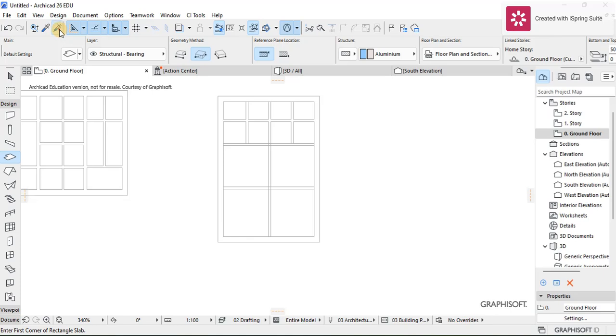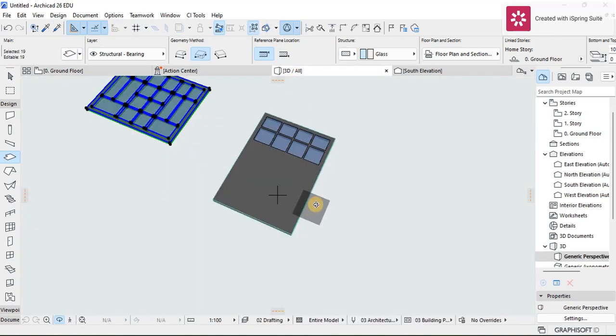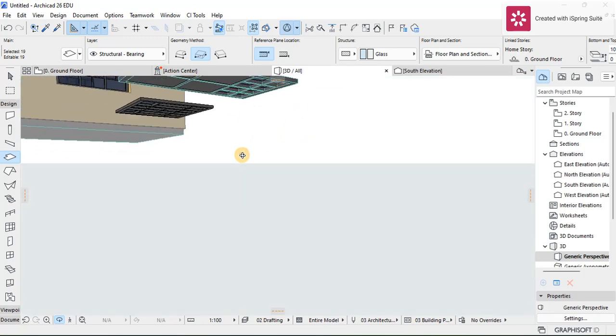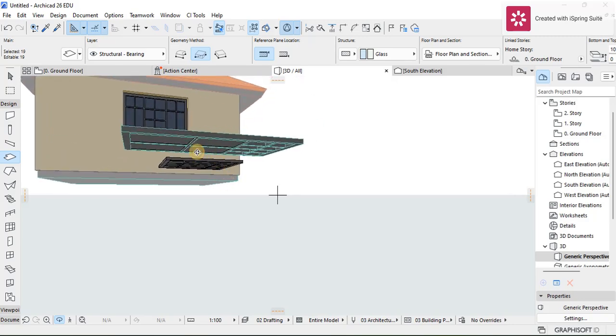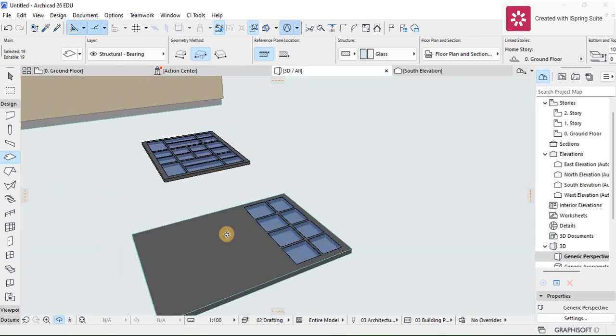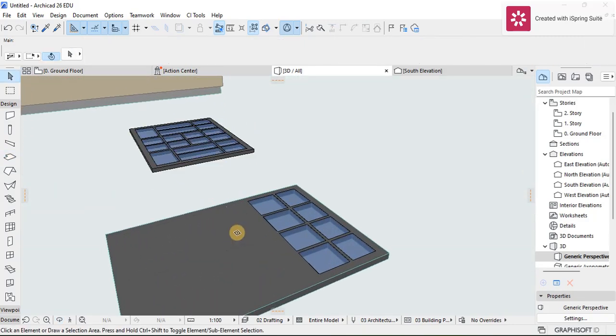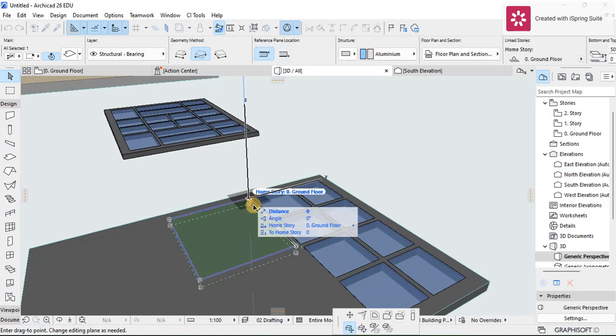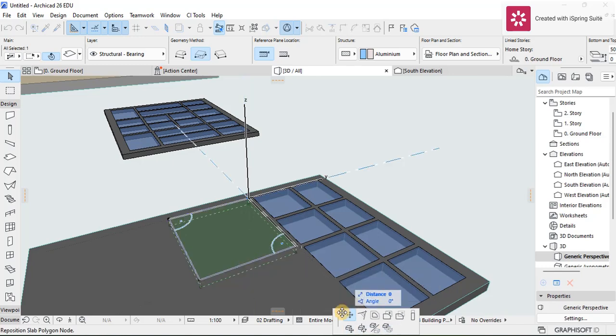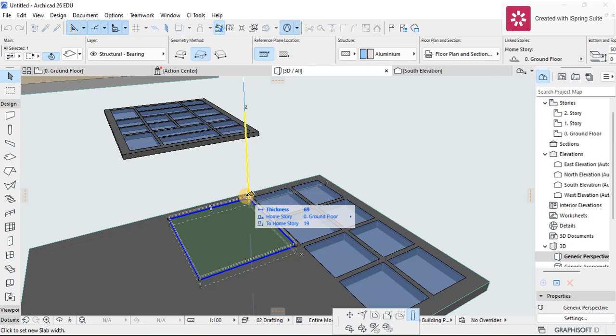Yeah, so with that done, we're going to go back to 3D, and you can see something like this is happening, but it's going to happen on the upside down section of it. So I'm just going to have to drag it so that the upright area too is protruded. So I'm just going to select the slab. I'm actually going to have to drag it upwards to make it a bit thicker. Somewhere, let's make the thickness a bit bigger, like 70.